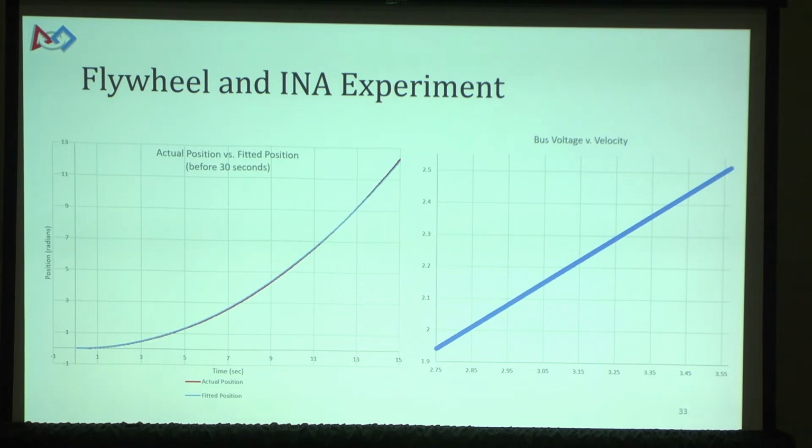For the test, we applied power to the motor for 30 seconds, and then we shut power off and continued to collect data for another 30 seconds. So this is data of the motor accelerating for 30 seconds. And as you can see, it fits very nicely.